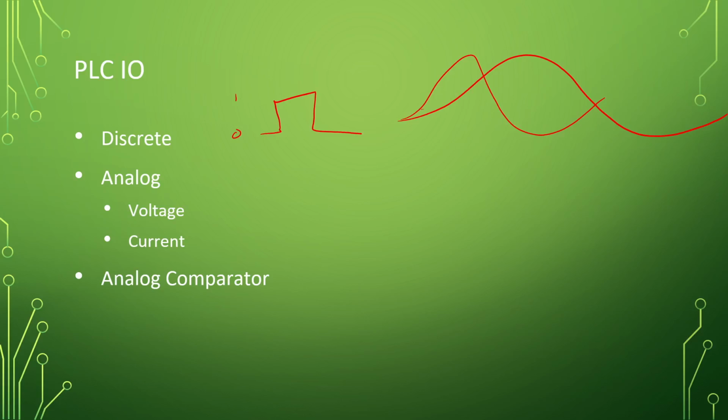However, we don't really like voltage because of electrical noise. Having an analog wire by an AC line will induce things and cause spikes and things like that. So we really don't like voltage measurements, and you can avoid them. Not saying you can always avoid them, but when you can, it's really best to go with the current measurement.